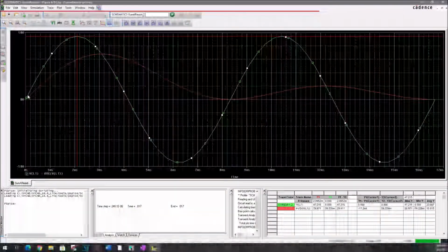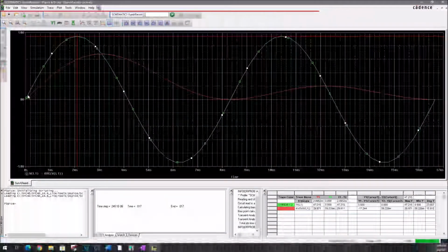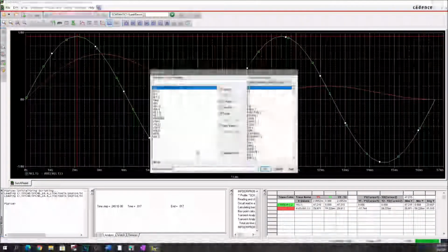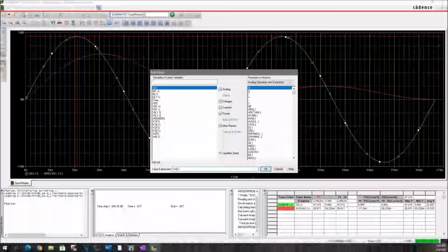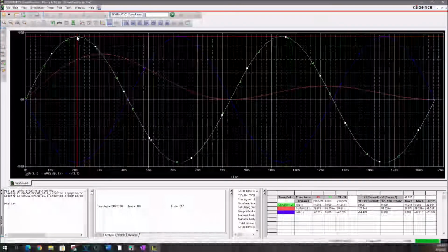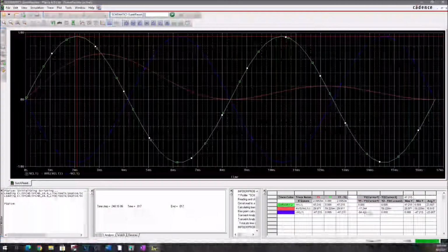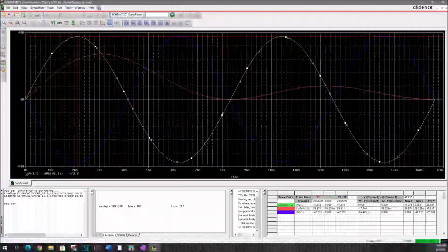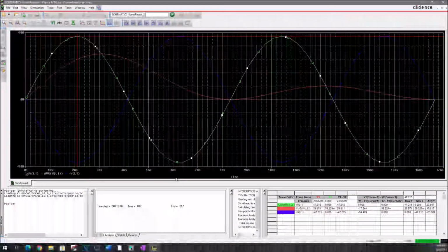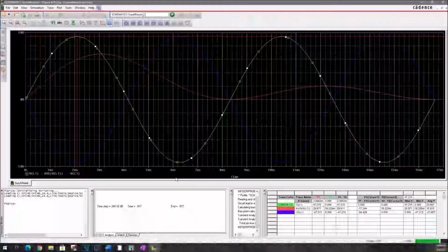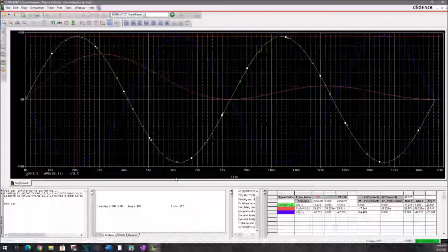We can also determine the peak-to-peak instantaneous power. Let's go to trace, add trace, then negative W(L1). With the cursor at the positive instantaneous power, we can see that the peak-to-peak instantaneous power is 94.49 watts here. Later, I will also show you why we got the peak-to-peak instantaneous power value in the simulation and the peak value of the instantaneous power.